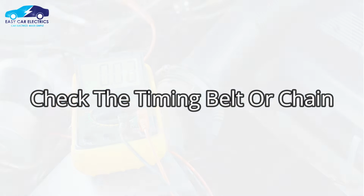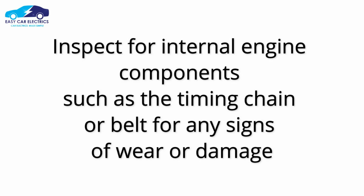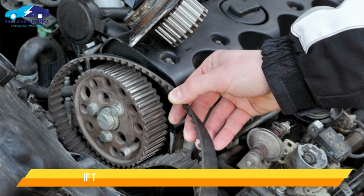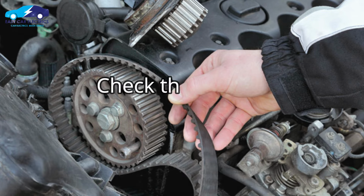Check the timing belt or chain. Inspect the internal engine components such as the timing chain or belt for any signs of wear or damage. A stretched or damaged timing belt can cause the camshaft position sensor signal to be inaccurate. If the timing belt or chain is damaged, it should be replaced.